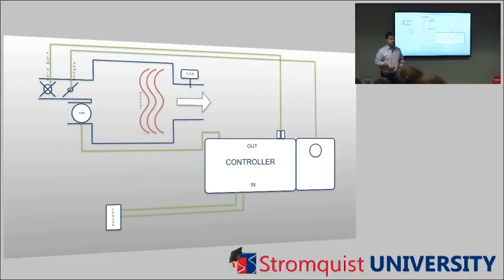You got it. Space temp and set point, right? Because that's what it's trying to get. So it says, I want my set point to be 70 degrees. And then it's also measuring space temp. So when I get to 71 or 72 degrees, it's going to start its program, what it's programmed to do, and bring it back, opening the damper, turning on the fan, whatever we've programmed it to do when it gets above or below set point. All right, good.